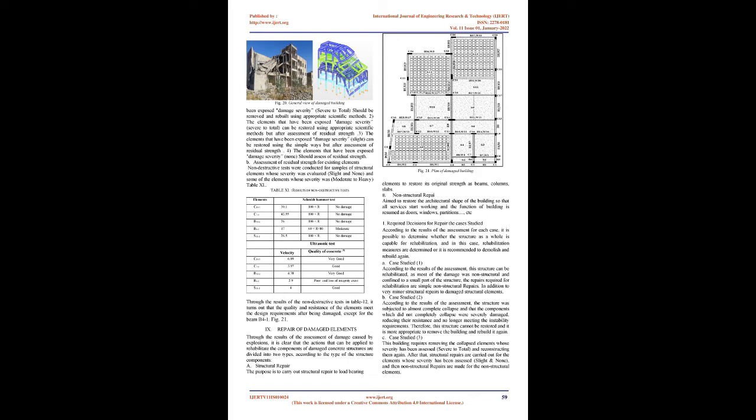2. The elements that have been exposed to damage severity, severe to total, can be restored using appropriate scientific methods but after assessment of residual strength. 3. The elements that have been exposed to damage severity, slight, can be restored using simple ways but after assessment of residual strength. 4. The elements that have been exposed to damage severity, none, should be assessed for residual strength.